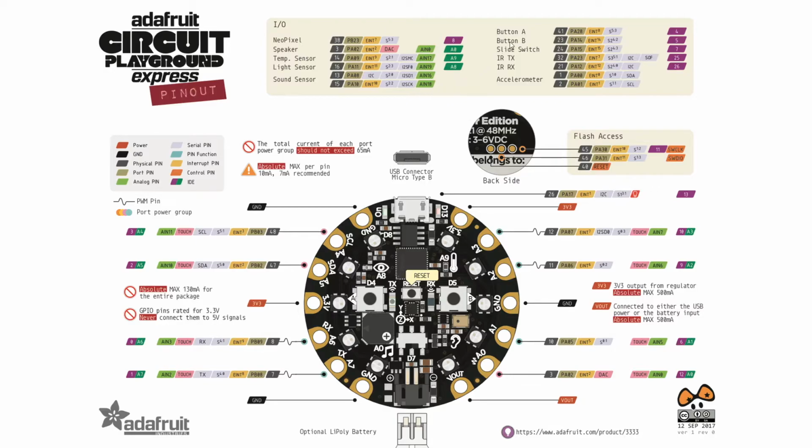So, for example, if we're going to be using the buttons, button A is going to be located on pin 4, which we can see all the way over here on the right, but it's also telling you that it is going to be physically at 41 on the chip. This is going to give you information about ports and other things like that. Because it's in purple, it's going to be a binary value, either on or off. This is telling you this because it is a digital I/O pin. The slider is on 7, so we need 4, 5, and 7 for our program.